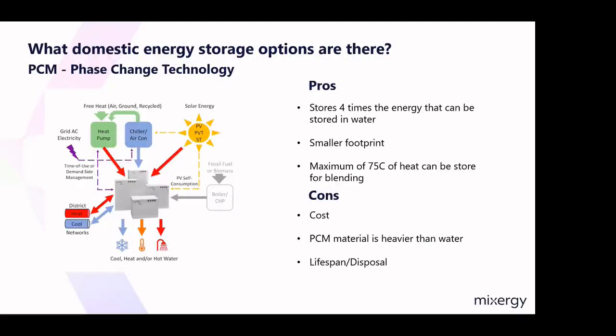Heat has traditionally been stored in water. This has been very successful due to the natural high specific heat capacity of water. So water can store around about 10 times as much heat as the equivalent mass of copper. However, despite its efficiency, where relatively little space is available, there are materials that can store over 4 times as much heat as water at the same volume.